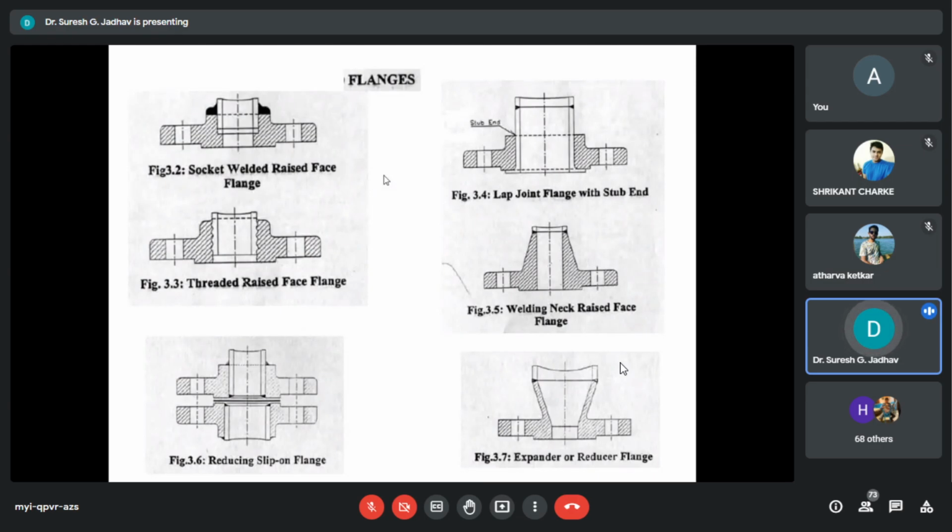A flange joint is composed of three separate and independent, although interrelated, components: the flanges, the gaskets, and the bolting, which are assembled by yet another influence, the fitter. Special controls are required in the selection and application of all these elements to attain a leak-free joint.